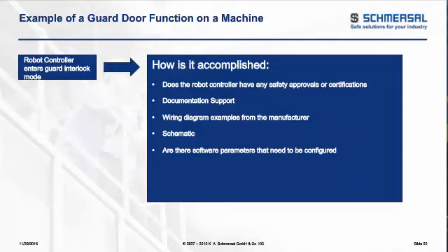It's easy to make the statement, but do you have the documentation that really backs you up? How do you know you're wiring it up properly? Sometimes it's easy to think that you are, but until you have the manufacturer's installation instructions to support what you're doing, you need to make sure and look at those wiring diagrams and wire it per the manufacturer specifications, because that's what they have approved to meet that specific safety level for your machine.